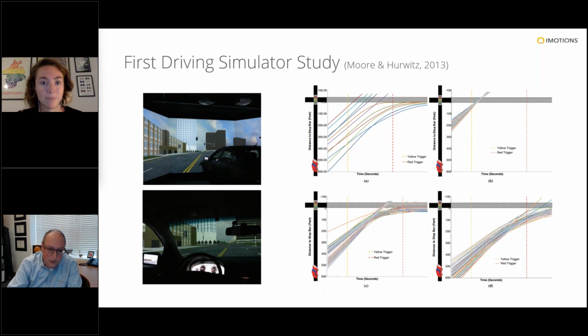And so these are a couple of screenshots from that original version of our passenger car driving simulator, this particular equipment produced by RTI on the simulator side of things. And that first experiment was an evaluation of dilemma zone conflicts and behaviors as modeled in a simulated environment. And so what we're seeing here are individual road users being exposed to different durations of yellow intervals as they approach a signalized intersection and their resulting choices.